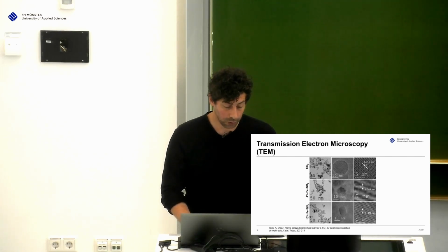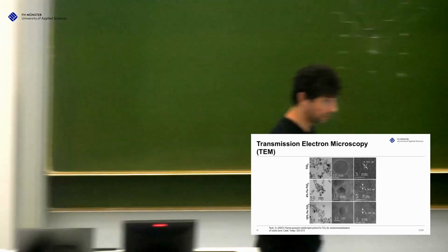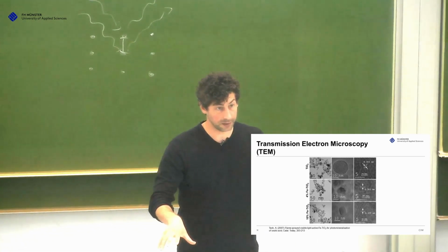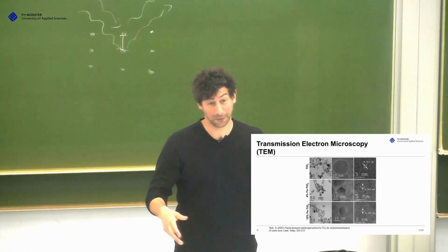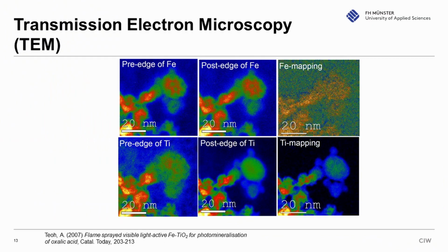Also the doping decreases the particle size. This is what you see here also. And this is what you have to consider. If you change one variable, you also play around with the other ones. And this could be beneficial, could be, but also very, very bad, okay? And this is why a good characterization is so important.